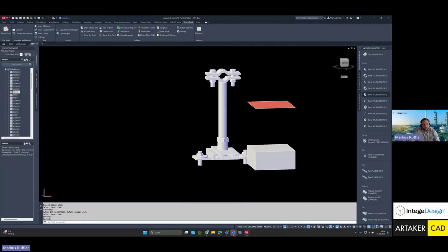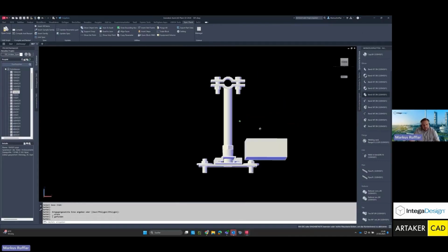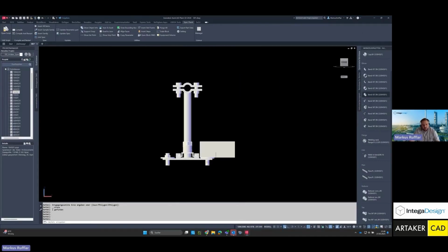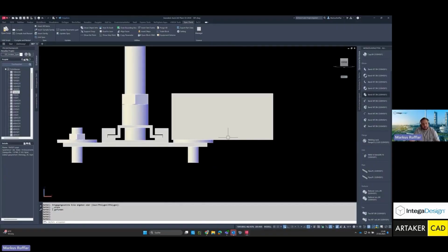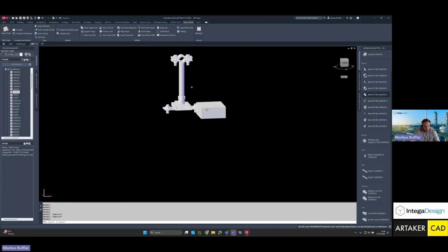And now you can see, you can delete that surface again. That's the old one. You can see that now, just like you might know from the vendor, it has really made the two surfaces dependent on each other. And depending on how I select the components or surfaces in the selection mode, the component will ultimately be moved to the other one. So that's something to pay a bit of attention to. All right, so that's relatively simple in terms of function, basically pushing one component onto another using two surfaces.